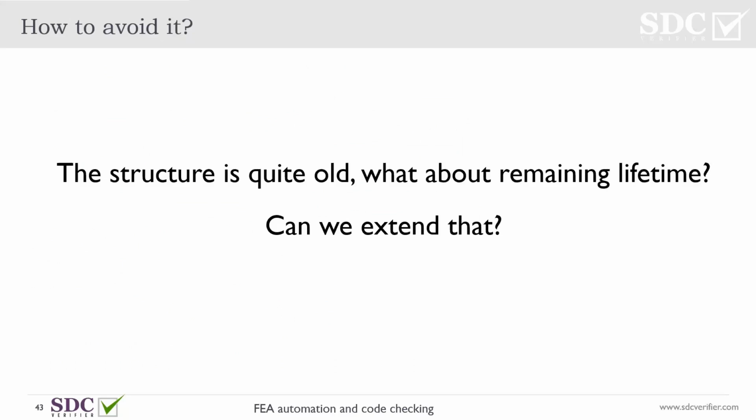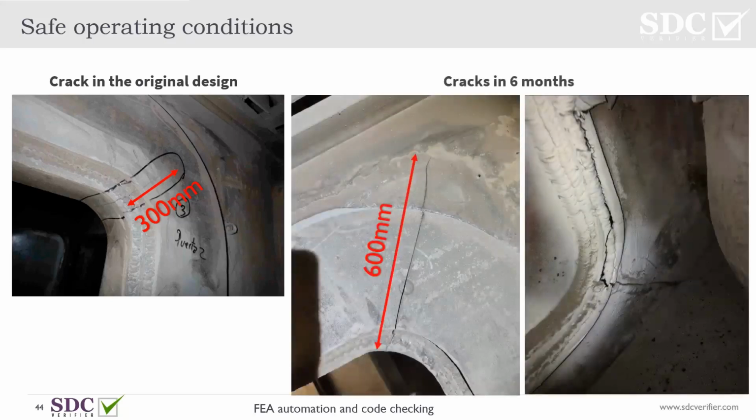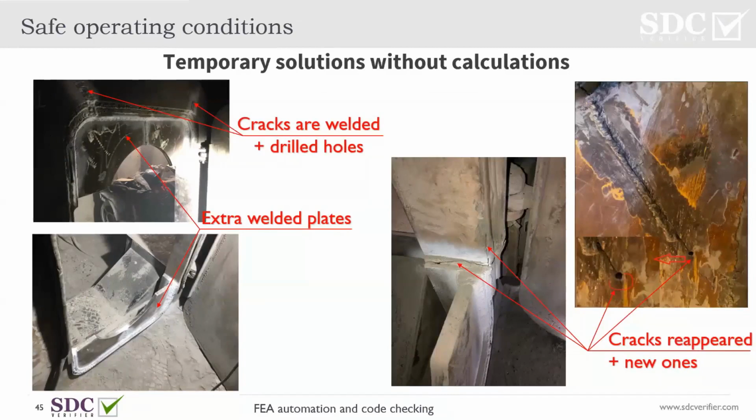It tends to be that the crane owner thinks, I got a certain crack, I will simply weld it, or I will come up with local improvements when it's continuing to grow. But these local solutions without calculations sometimes lead to additional cracks repeated in the surrounding area. Yeah, so the finite element calculations are the must-have on the list for these things.